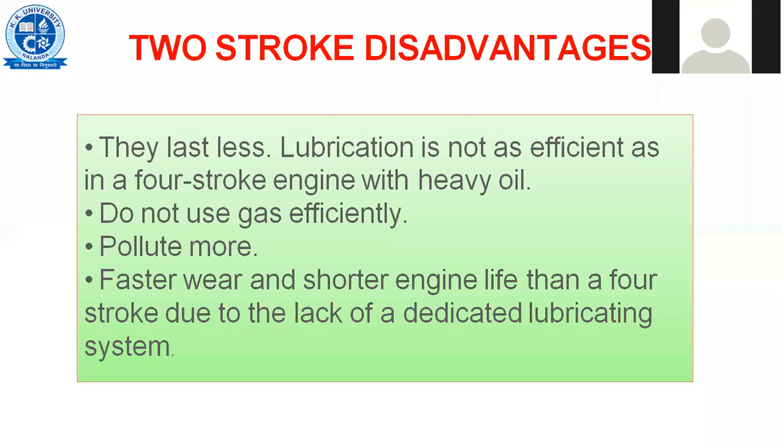Well, it's very high temperature. That's what we were talking about, like a kind of explosion which just happens inside the engine cylinder. So the temperature at the time of explosion runs into several hundred degrees centigrade, anything between 1800 degrees plus for that moment at the time of spark. And inside, when it starts expanding, the temperature may be of the order of a few hundred degrees centigrade, maybe 600 to 700.